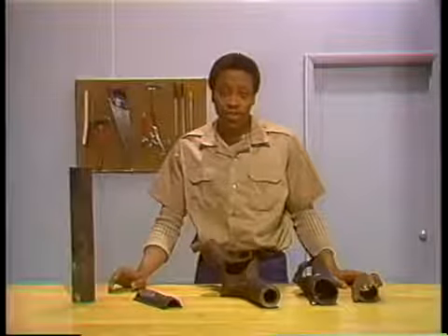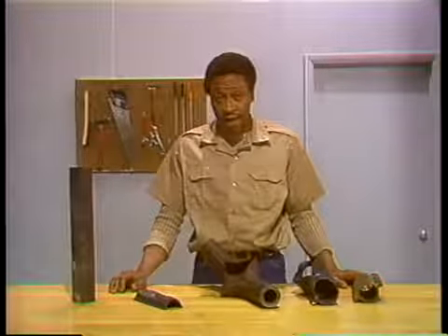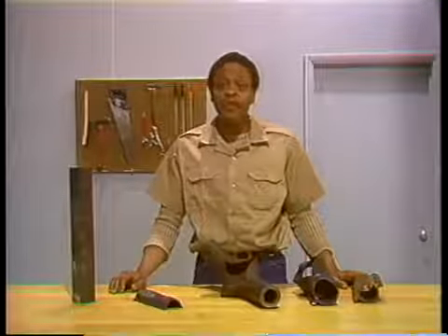It appears as a uniform enlargement of a portion of the tube. The overheating that causes it is milder than the temperatures responsible for ruptures and cracking. But if an enlarged tube stays in service, it will eventually rupture or crack.